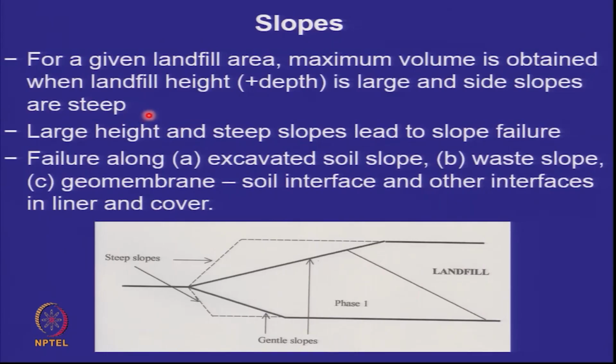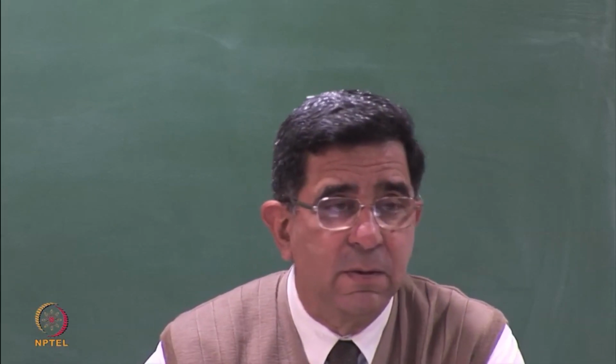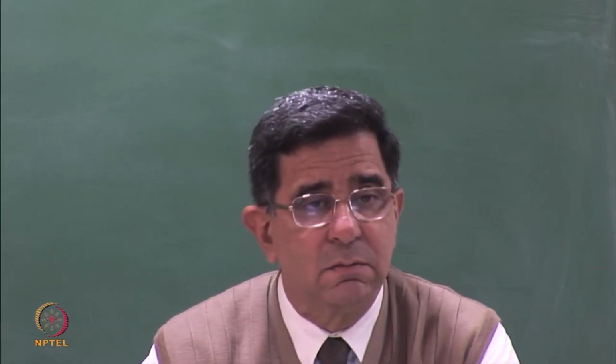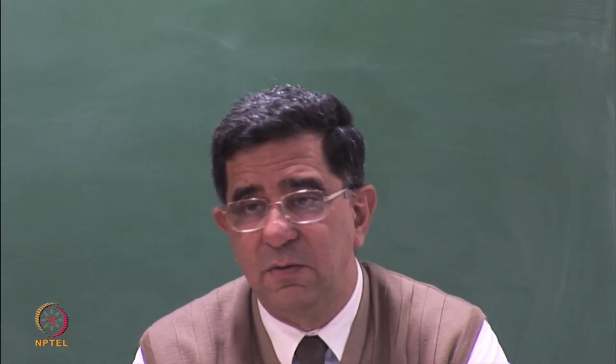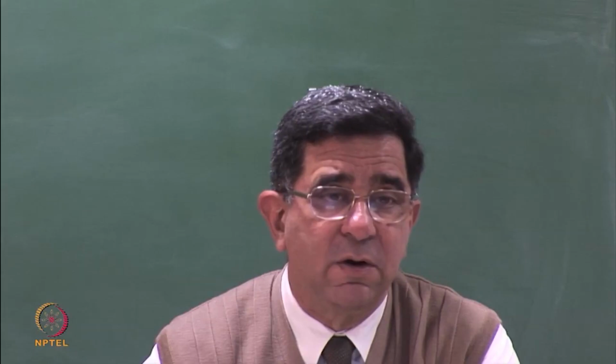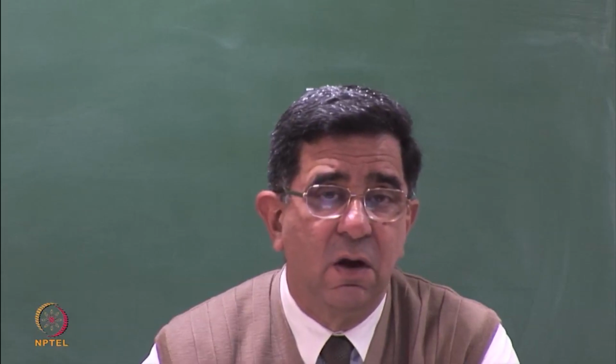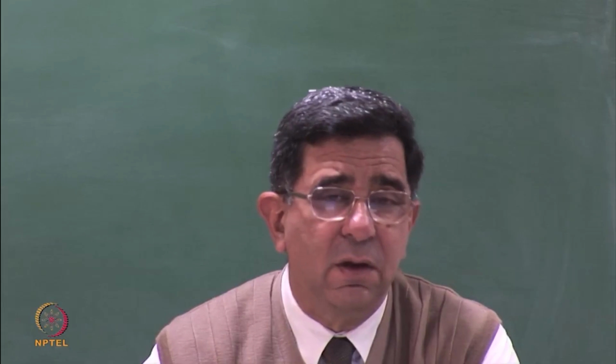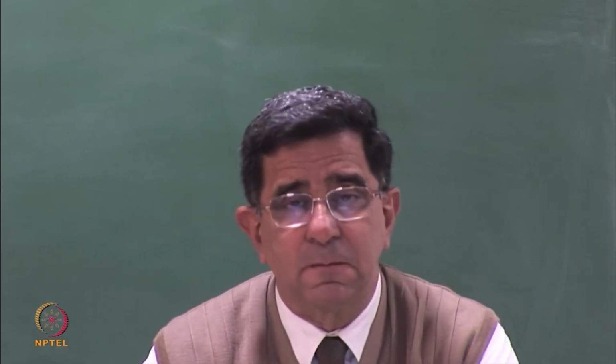So as we have already done, what will typically govern the depth of a landfill? When there is a high water table, that means the water table is a few meters below the ground surface, we can't go below. Similarly, when there is rock a few meters below the ground surface, we can't dig below. So we will not have much depth if there is a water table at high level or if there is rock very close to the ground surface.